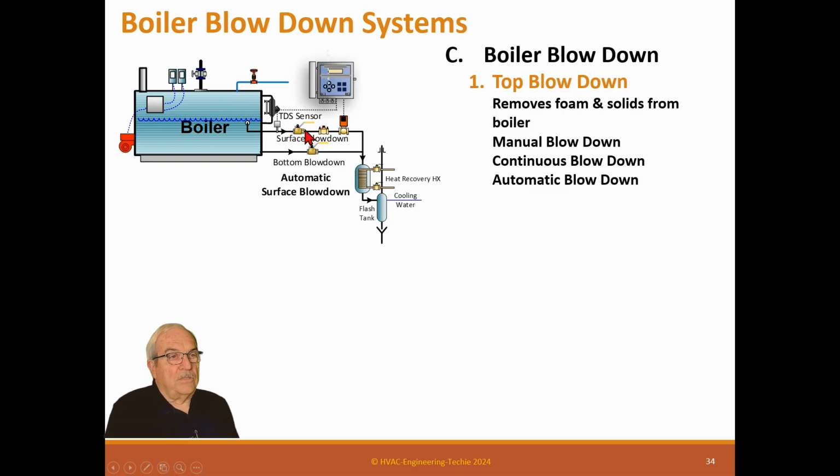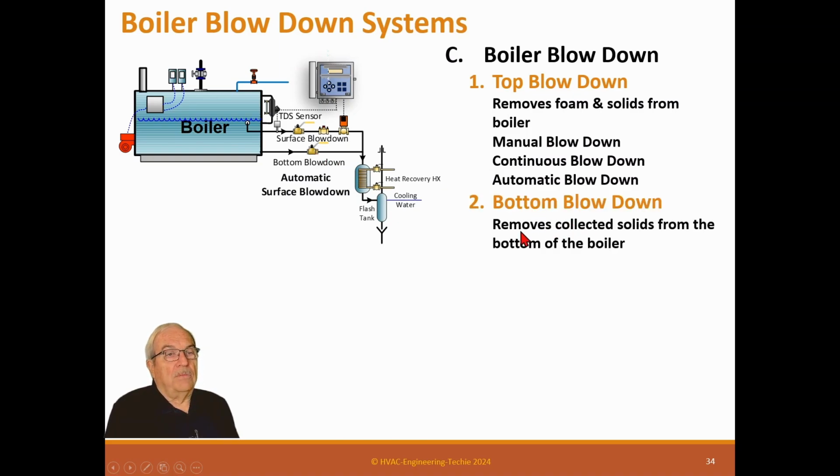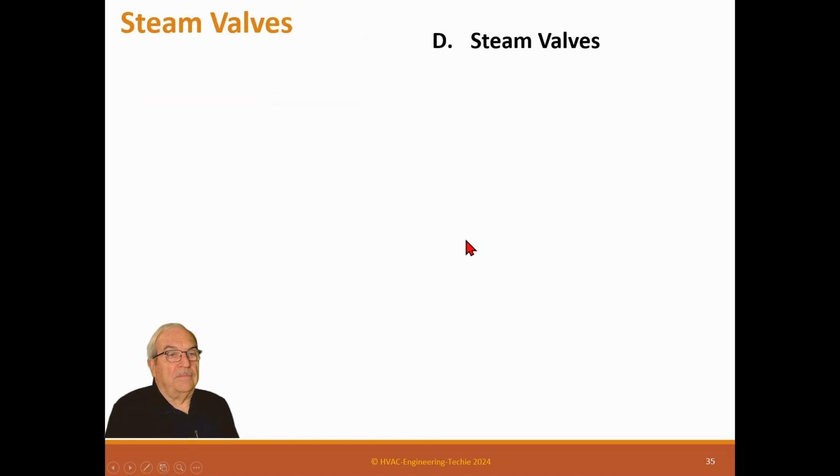I've installed these before on boilers where it does it once a day or twice a day, and this one still remains manual. Bottom blowdown removes collected solids from the bottom of the boiler, normally manual blowdown.